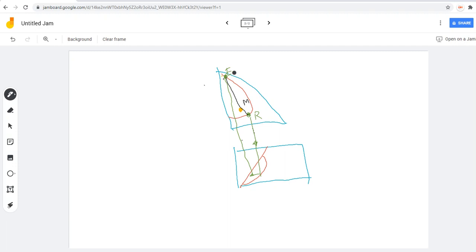The reading for the composition here is your extract composition. So extract will be having composition Y because it's extract, YA and YC. Your YB will be just 1 minus (YA plus YC). Now the same thing with the raffinate. So your composition for the raffinate would be XA and XC.